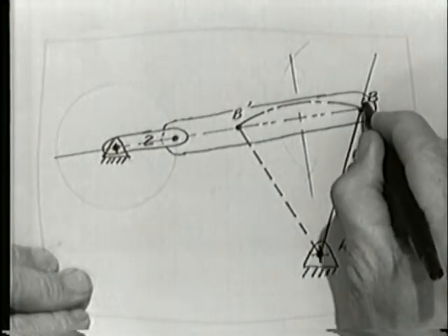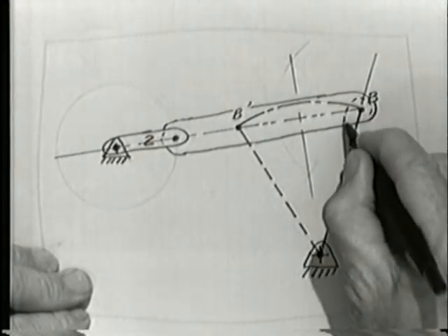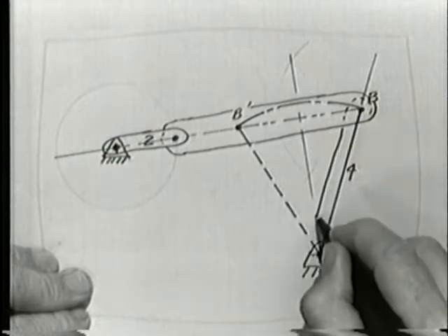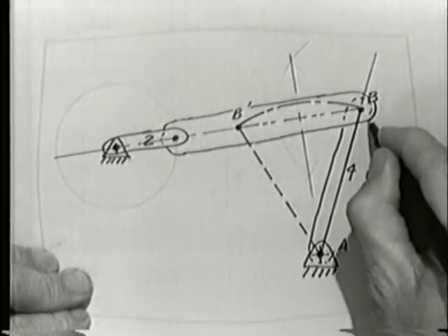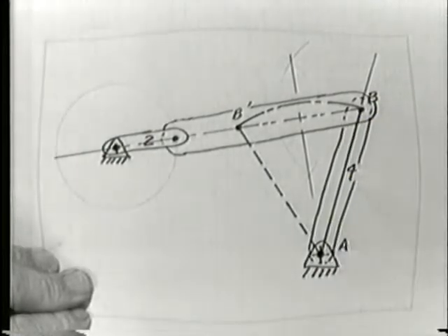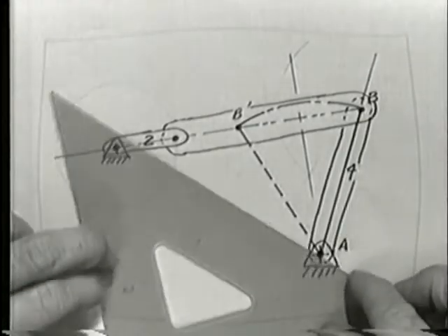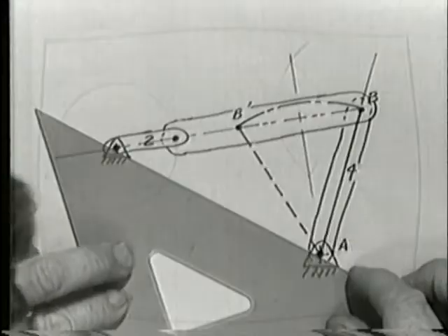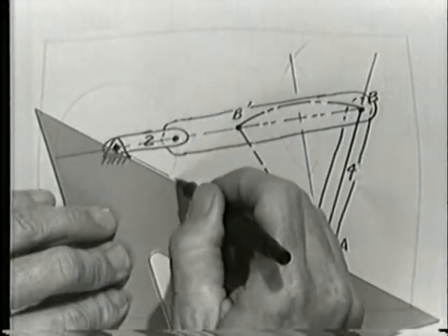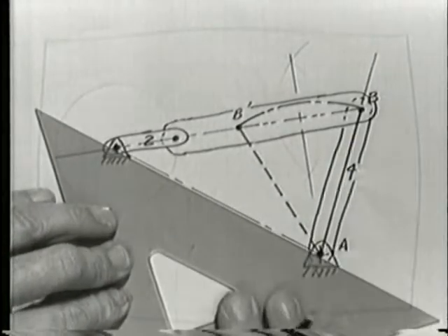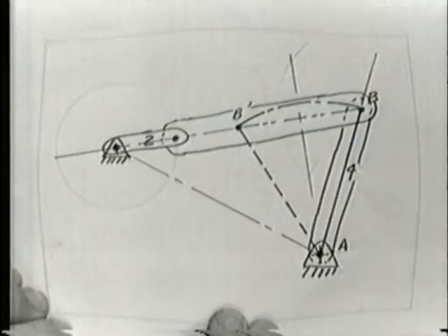And we can get a little fancier here and show some shape to link 4, which I didn't show before. And that's the solution right there. Link 1, which is not yet numbered, is simply the line of centers. It is the piece of paper, and it's the distance between the two fixed pivots.